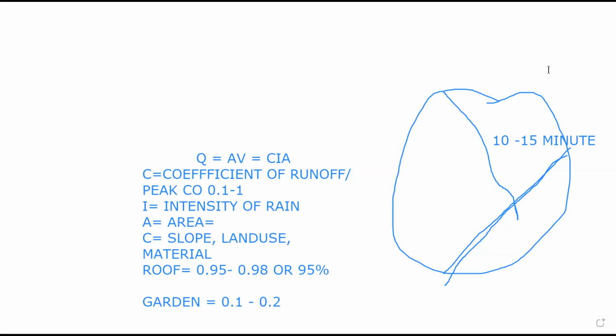In the first 15 minutes of rain, I take the measurement, and I can predict for you where it will rain. And then based on the geography of the area, I can tell you where the flooding is going to occur. Of course, it's going to be downstream, but where in particular downstream? I will now check what we call travel time. Travel time of the rain will give me an idea of where the rain will start to cause problems. So people who predict rainfall use what they call an early warning system. That's how an early warning system works.